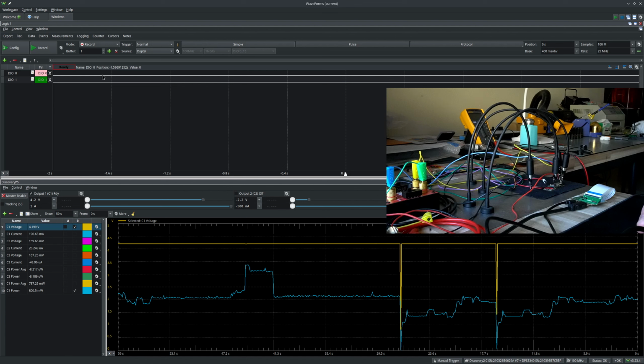So currently there's nothing here, but if I start up this system and then time it right so that I hit record when the system will start transmitting this initialization data, I can capture it on data lane 0 before the lanes go into high speed mode and start transmitting video data.